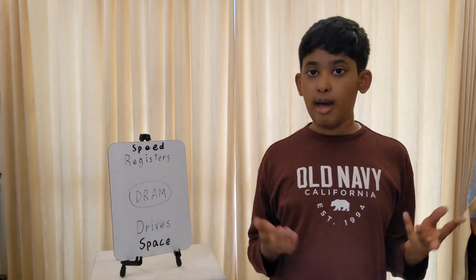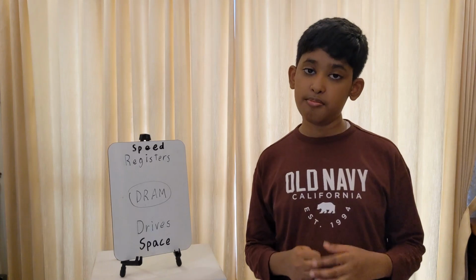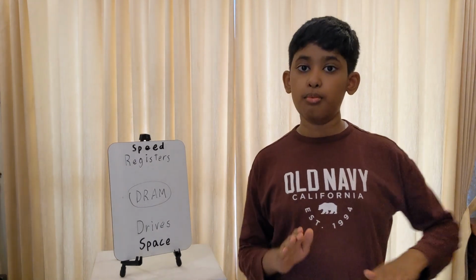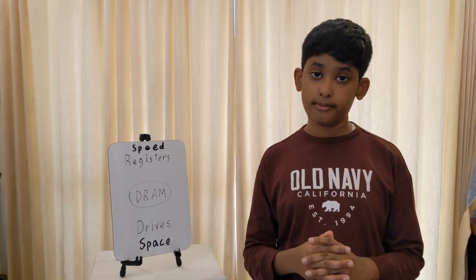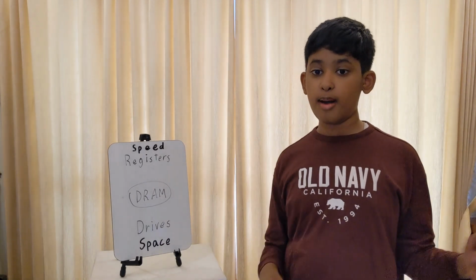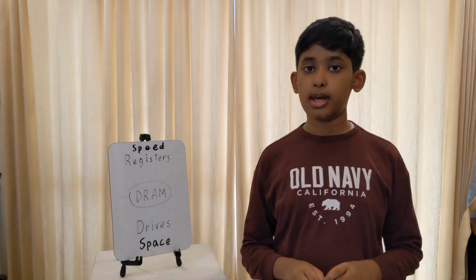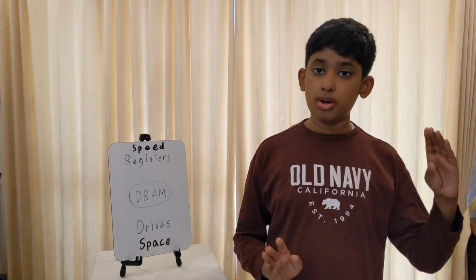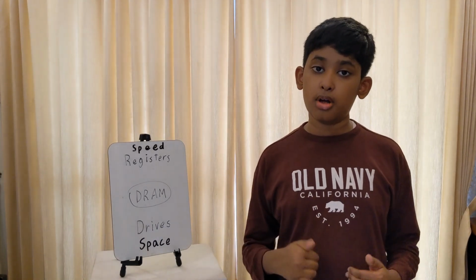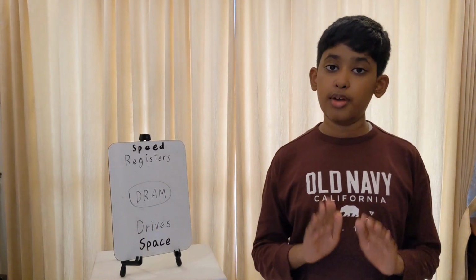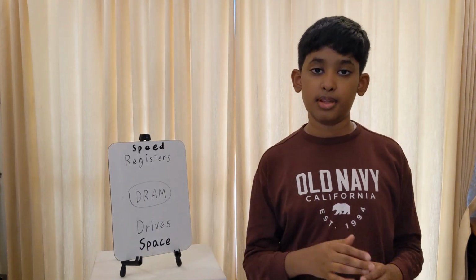Each stick of DRAM might contain 8 or so chips. And each chip contains bank groups of memory, which are subdivided into memory banks. Each of these memory banks stores a small amount of data, so we're only going to be looking at one of them at a time. Your stick of DRAM has some internal chip logic for deciding which memory bank you need to use when you want a specific bit of data.